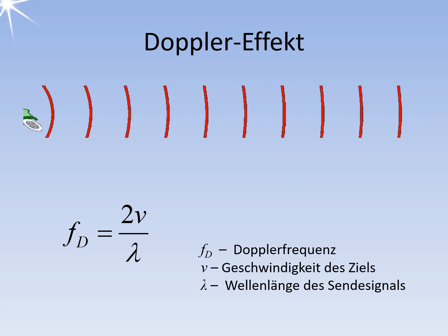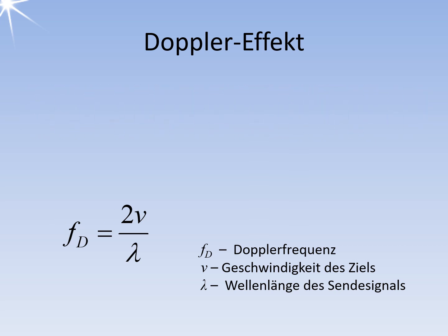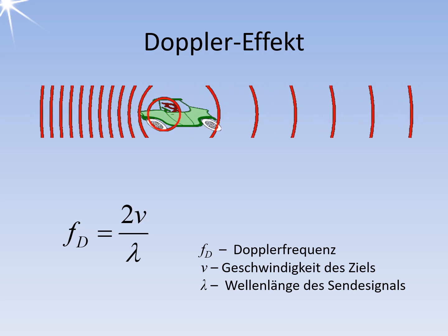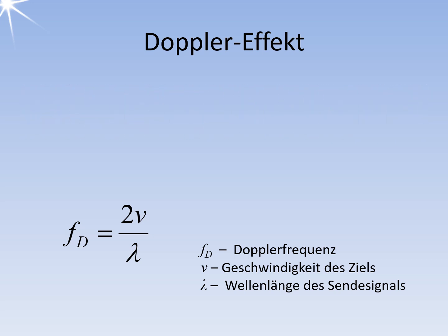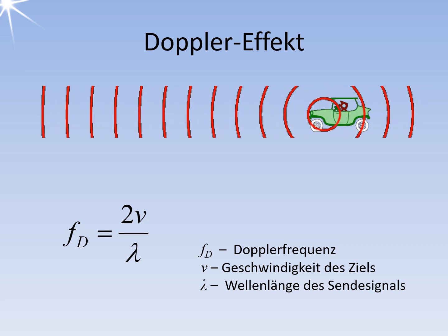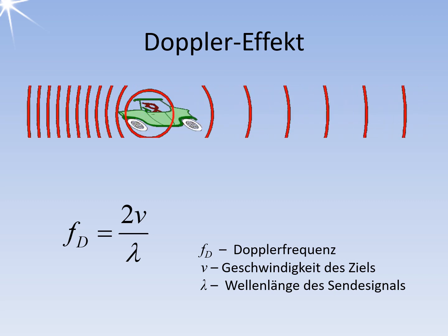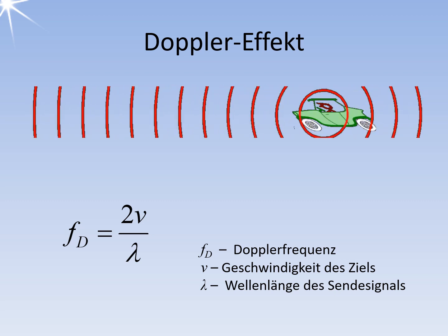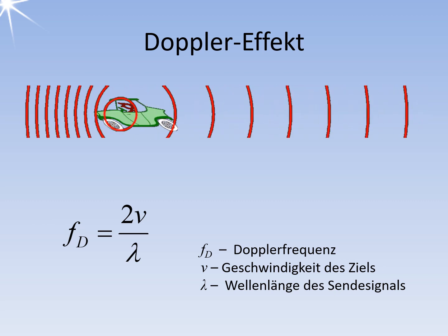From the Doppler frequency, the velocity v_r can be calculated directly. It is only an approximation equation based on the fact that even a very fast airplane flies much slower than the speed of light. Factor 2 expresses that the Doppler frequency occurs twice with radar, the first time during the way from the radar to the target, and the second time for the now already with the Doppler frequency of the outward way affected reflected signal on the way back to the radar.